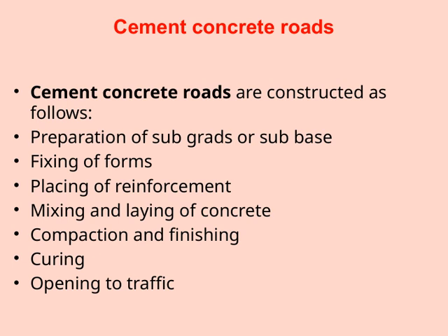Then, we proceed to curing, which involves keeping the concrete moist to allow proper hydration and strength development. This step is crucial for the longevity of the road. Finally, after curing, the road can be opened to traffic. This entire process, from preparation to opening, is designed to produce durable and long-lasting cement concrete roads that can withstand traffic and environmental conditions. Connecting all these steps highlights how each phase plays a vital role in building reliable infrastructure.